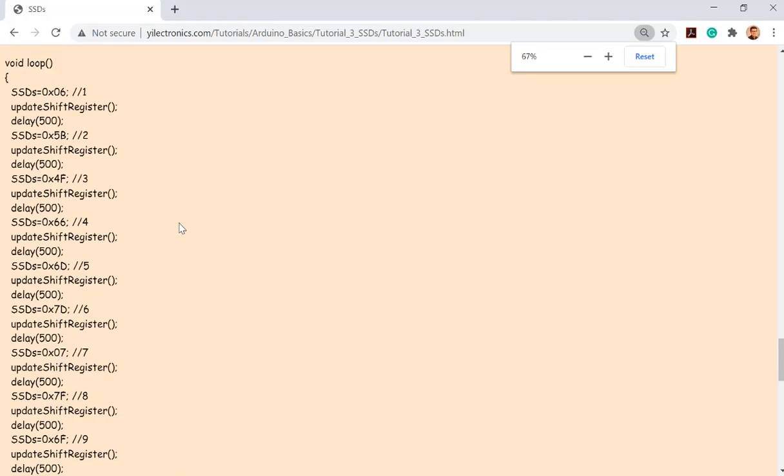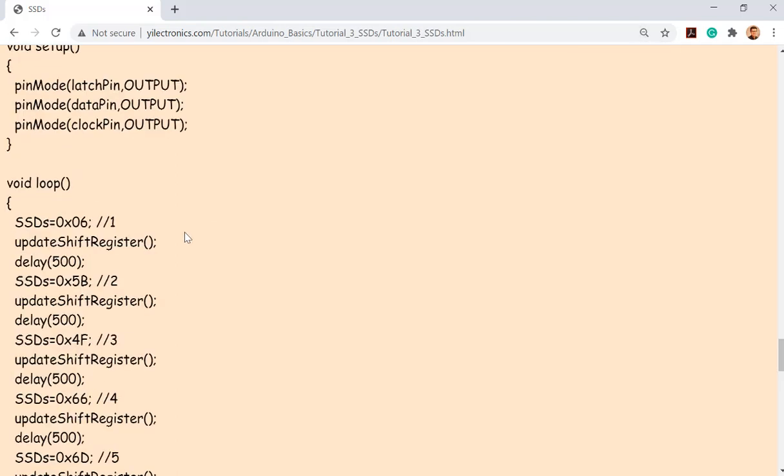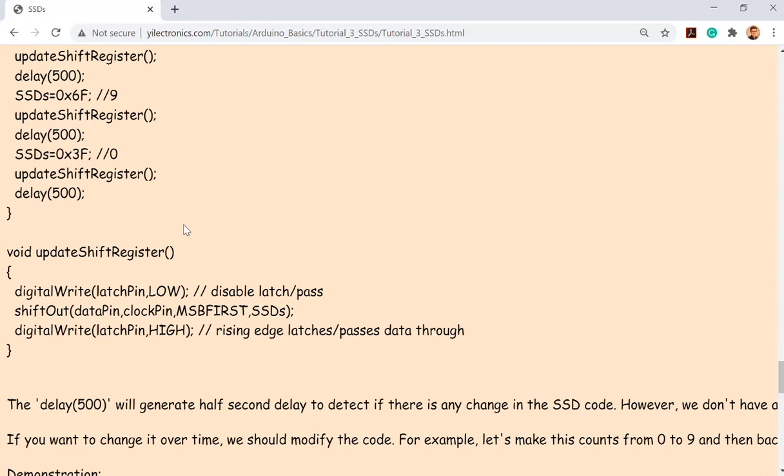One thing you need to know is there are two options to pump the binary data to the shift register. One is the shiftOut function, because it is embedded into the Arduino's IDE, feel free to use it. It's going to manage the protocol for you, so you don't have to manage every pattern, every high and low in the protocol. It's complicated. It's not worth it. So you are using the shiftOut function to do that job.